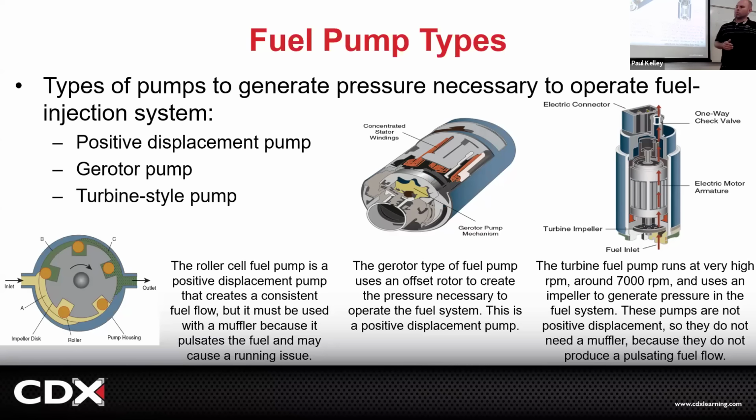I've also seen a fuel pump where one segment or two segments in the motor fail. At that point, it'll turn, but it'll be fast and then slow and then fast and then slow. If your electric motor can't keep the RPM you want, do you think it's going to make the fuel pressure that you want? No, exactly. So for the most part you wouldn't need to, but if you got a weird issue where it's not making correct fuel pressure, you can actually scope the motor for the fuel pump and look at the waveform and give a really detailed diagnosis of what's going on with that fuel pump motor. I just don't do that unless I need to.